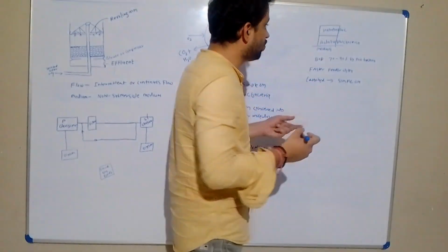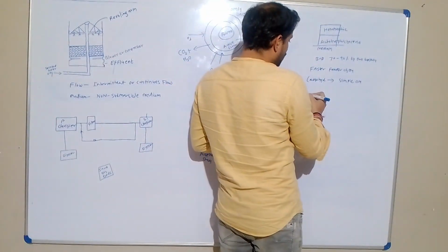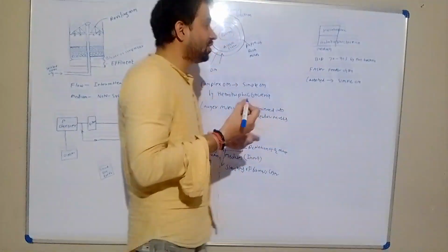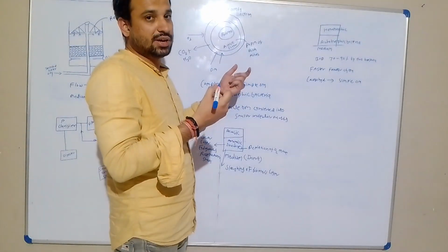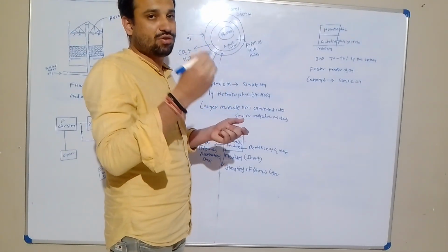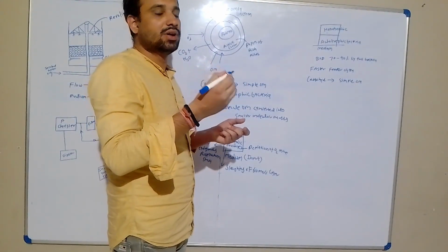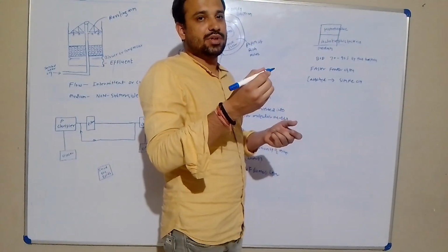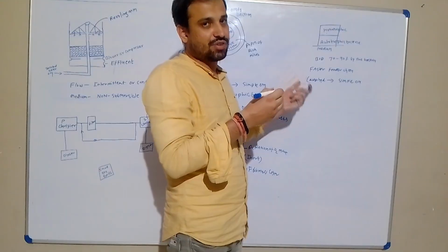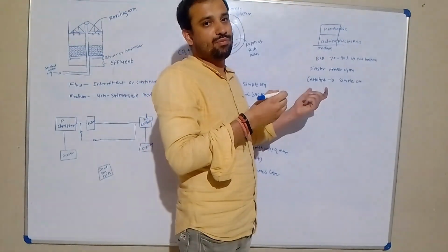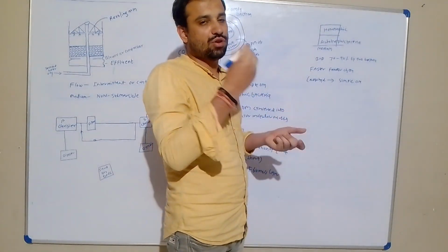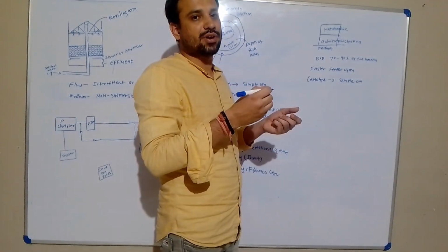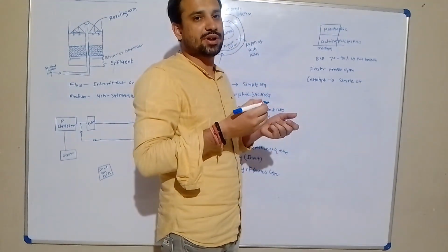So regarding availability of nutrients, the inorganic, ionic form of pollutants and the organic form of pollutants are directly diffused into the biomass layer. Carbon is the food source for the microorganisms. It is available in ionic form, a soluble molecular form, a soluble organic form, a complex form of organic matter or the simplest form of organic matter.